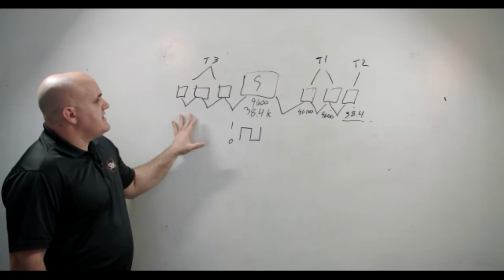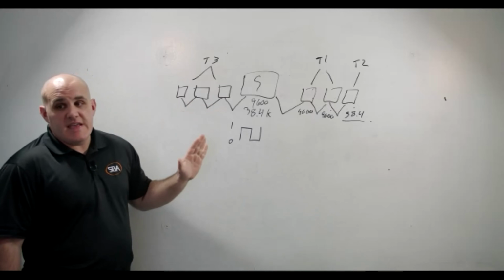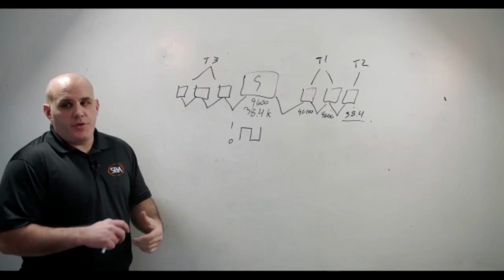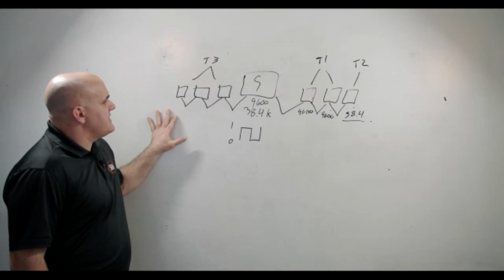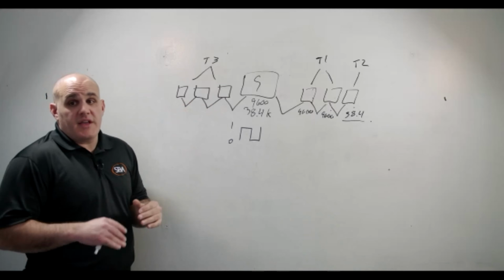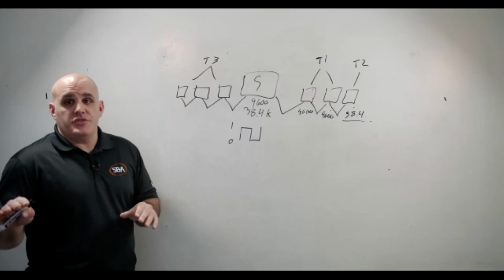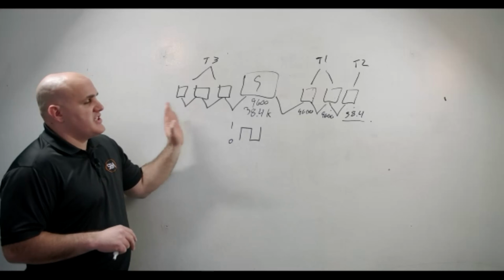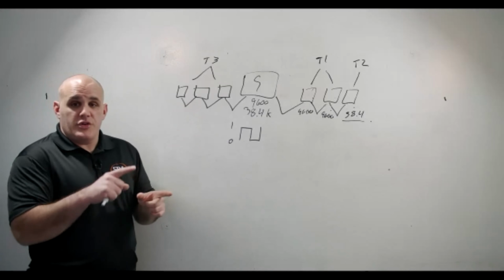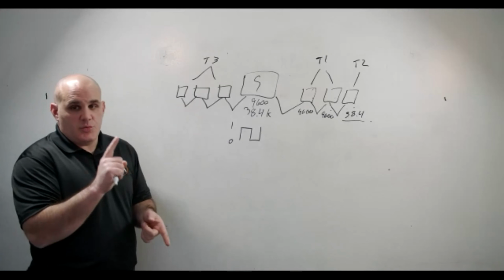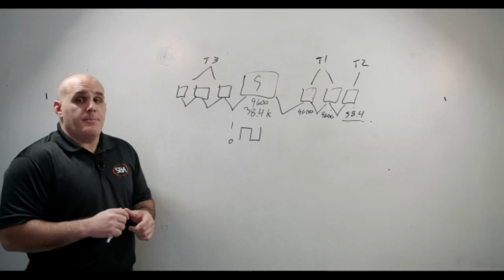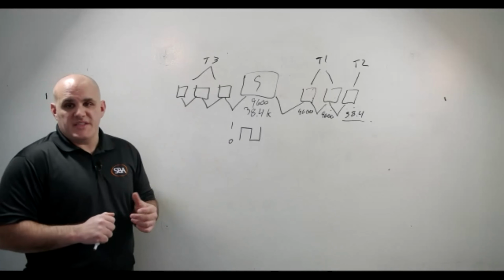Now, when you're dealing with that, MAC addresses have to be unique for that local MSTP network. Device IDs have to be unique for the BACnet network. So that device ID can have a conflict, and that will reflect in a device going up and down where you have two MAC addresses. Because when you do discovery, you're going to discover whichever device you get a response from first. And the same with MAC addresses. So that would be the sign where you have basically blinking devices. One goes up, one goes down, one goes up, one goes down. That's a sign of device ID and MAC address duplication or mismatches.